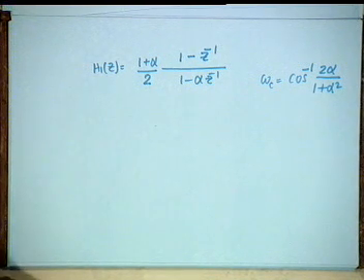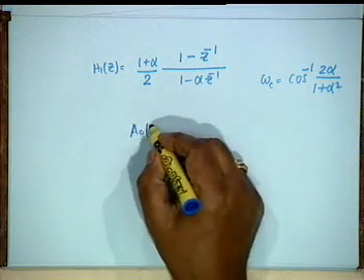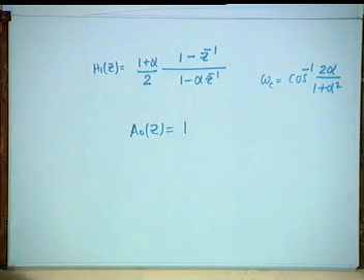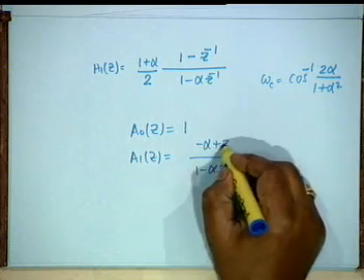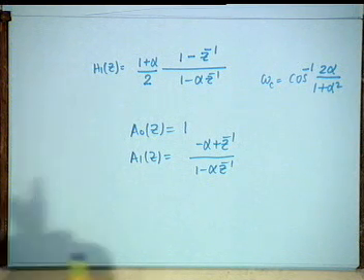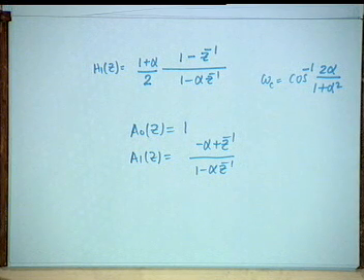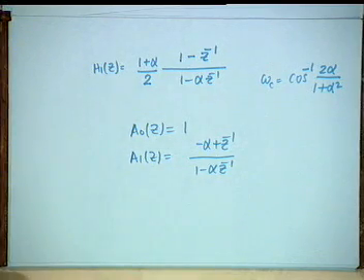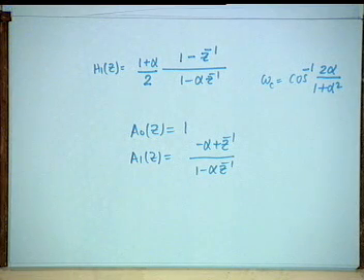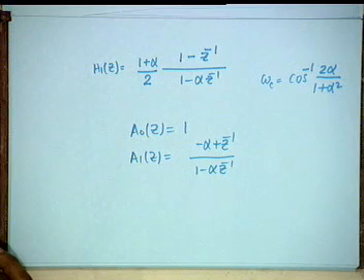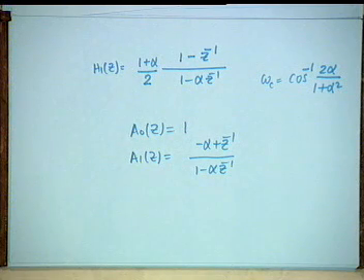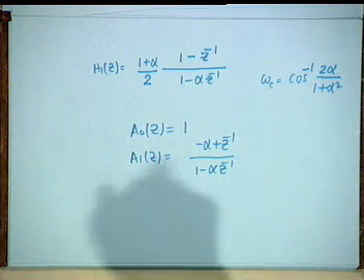Agreed? So, all that you have to do now, realization of A0 of z equal to 1 is no problem, it is a straight connection, and A1 of z we shall see the realization. We can do this realization by using only how many delays? First order. So, one delay, and we shall show later that we can realize with only one multiplying constant, and that is alpha. All right. So, it is a beautiful set of filters, first order, low pass as well as high pass, realized with one delay and one multiplier, very economic, most economic realization of two doubly complementary filters.